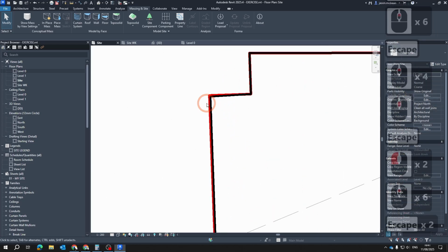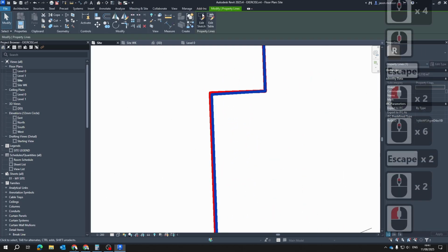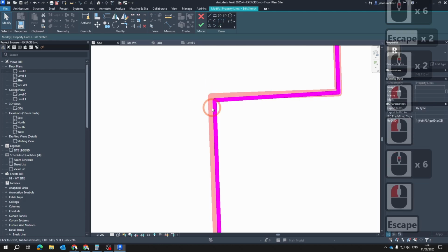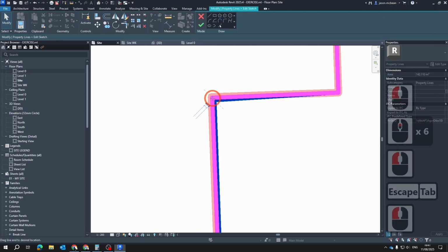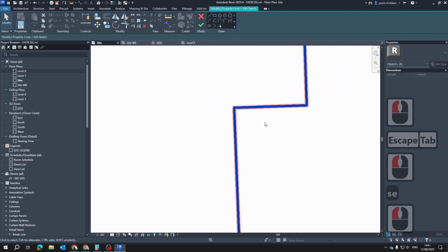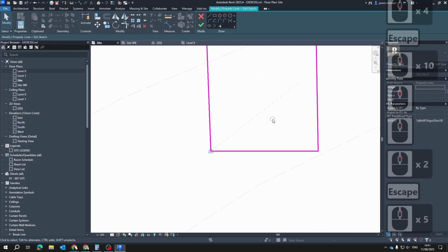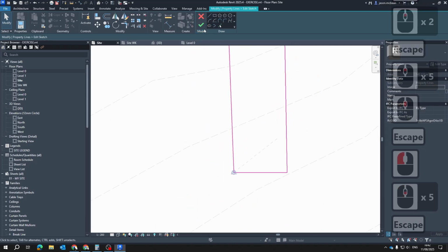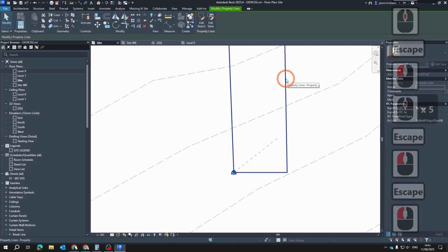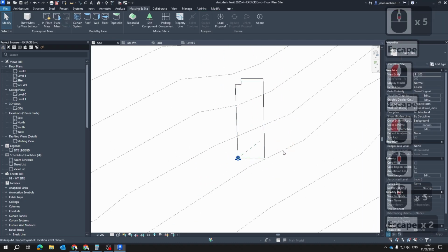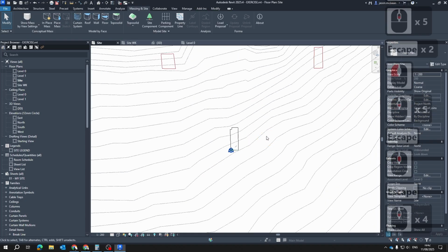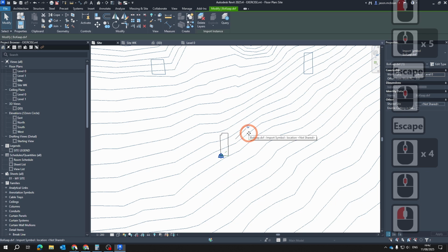So I made a mistake. So just be careful when using this information that you snap these things to the right location. Okay, so that must follow your site boundary exactly. Finish. Okay, so we've got our site boundary showing, and it'll be visible in every view, and we've got our contours. The next step we need to do is quickly we need to make our topography.